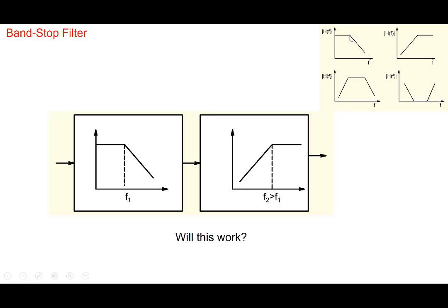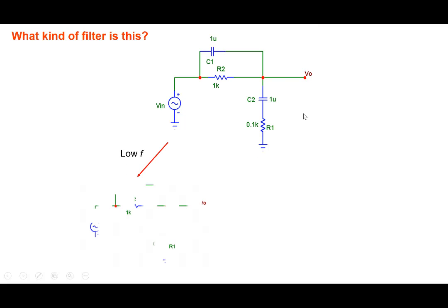But it's not easy. You can see that a simple RC circuit attenuates at a rate of 20 dB per decade. And if I build two RC circuits, maybe it does 40 dB per decade. Now, if you want 100 dB per decade attenuation, well, you will require many RC circuits, or you will require some other approach. That is here. Okay, so let's...